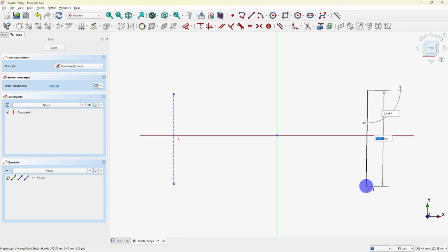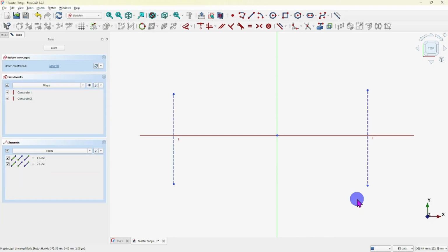You see to the lower right hand side of that purple circle, there's a line that goes straight up and down. That's showing me that it's locked into a vertical constraint. So if I hit enter, then that line should be perfectly straight up and down, perpendicular to the XY line is what I was trying to say.